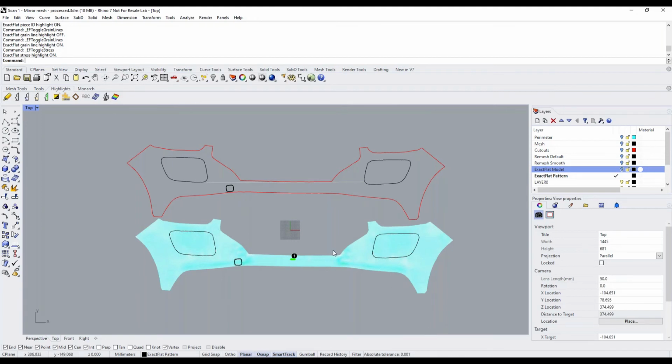Sure. When we use the global target strain, we have the option to apply either primary or principal, or transverse strain. I chose principal strain, which is in the direction of the grain line. So I essentially compressed the part from side to side when I applied that strain, compressing that part of the pattern by about 2.5%. Transverse strain is the opposite, perpendicular. I didn't do any transverse strain, so we didn't compress it in that orientation whatsoever. It's just an easy way for you to apply a strain to your part, such that you'd have to essentially stretch your part by 2.5% to get it to fit the surface area of your original 3D model.